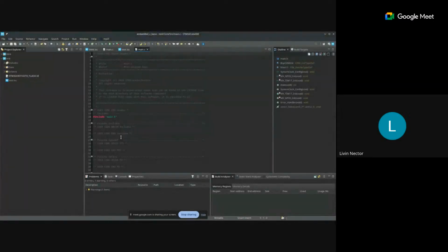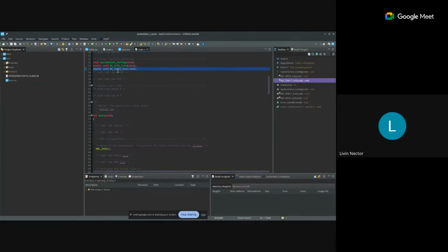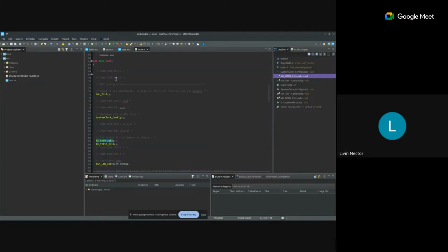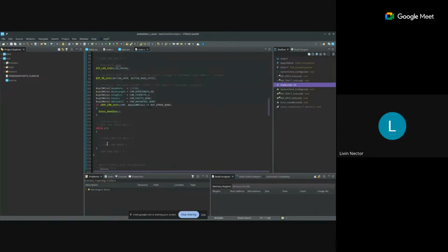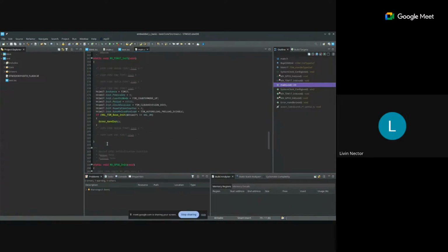And you see, just like how Arduino comes with setup and loop, with setup you can see there is some code that does initialization and processing. You can see the TIM17 timer and the GPIO initializations have been done automatically. And there is a function called HAL in it, and there are different things over here, right? Which is about how we program in this system.